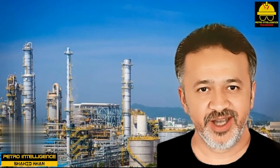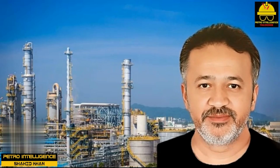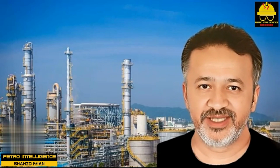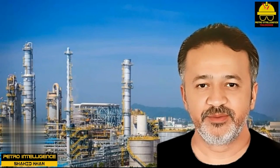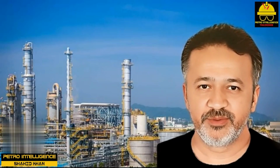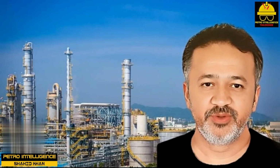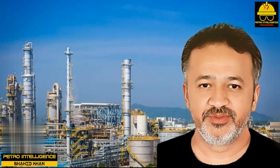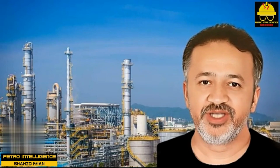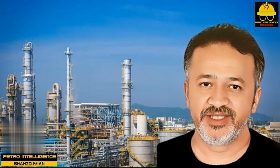However, compared to a modern valve tray, bubble cap trays were difficult to install because of their weight. They have about 15% less capacity because when vapor escapes from the slots on the bubble cap, it is moving in a horizontal direction. The vapor flow must turn 90 degrees. This change of direction promotes entrainment and, hence, jet flooding. They are more expensive to purchase. They are more difficult to clean.